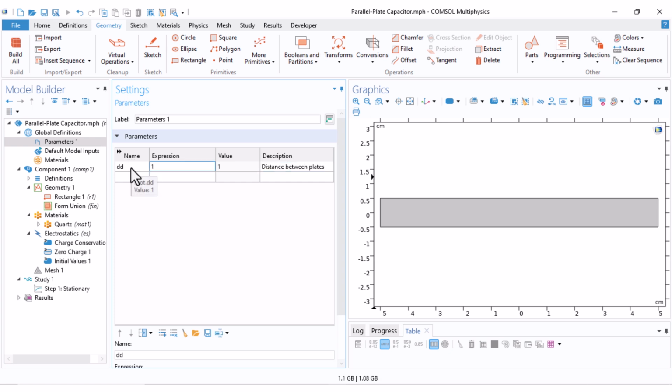Now I say why I set my parameters as 2 letters. For some letters, it is possible that this letter would be a predefined variable in COMSOL. For example, V is reserved for voltage, and so on. And to reduce the interference between my parameters and the reserved variables, I also use complex names for parameters, or I just repeat the name.